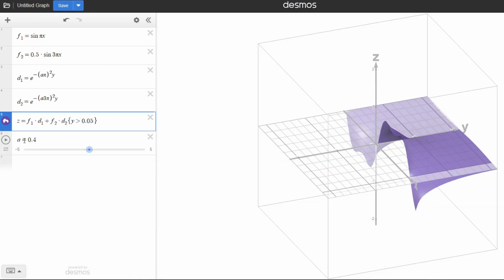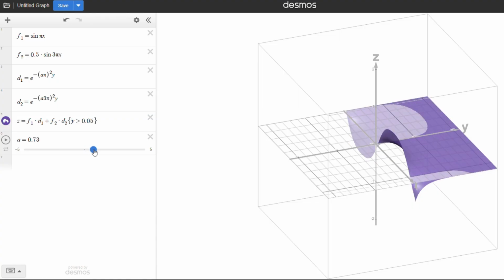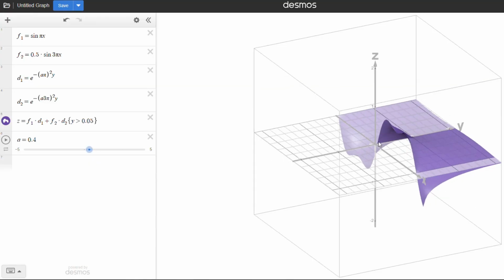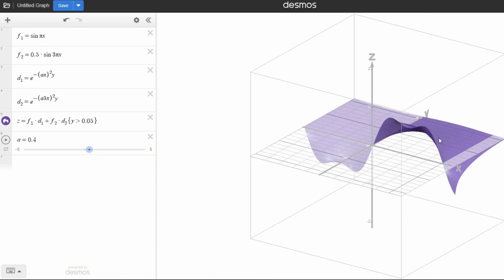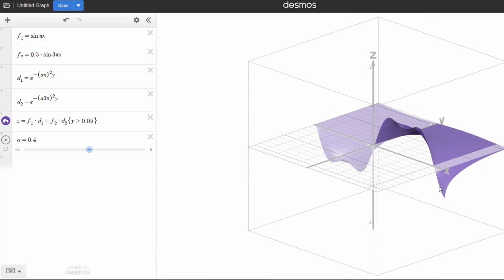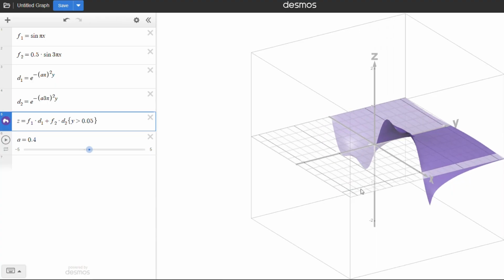And the diffusivity factor, which is a here, presented in the exponent part here, determines how fast the heat will decay. So if we increase it, you can notice that it decays faster. If we decrease it, you can notice it gets slower, like this. So yeah, here is the general solution. Here's the plot of the general solution. That is the initial condition of the heat, and it decays over time.